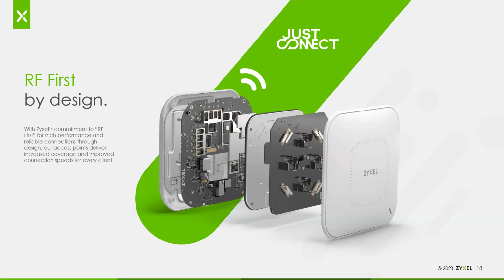And then when it comes to the RF first side of things, we have a lot more shielding on our boards than you will find in most of our competition. That's designed not just to help reduce EMI, electromagnetic interference. We've also designed most of our access points to be able to filter out 4G and 5G signals, which do neighbor a lot of the Wi-Fi channels and can cause interference, particularly in buildings that use a DAS system to bring cellular coverage inside the building itself.